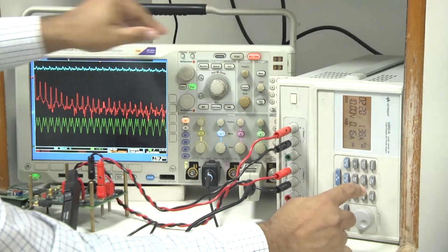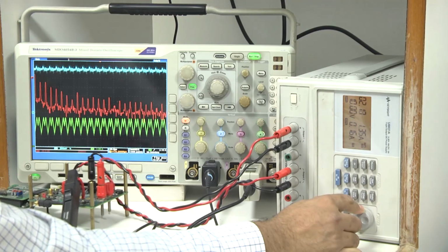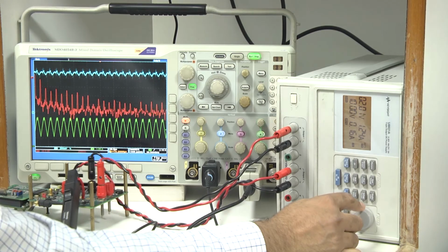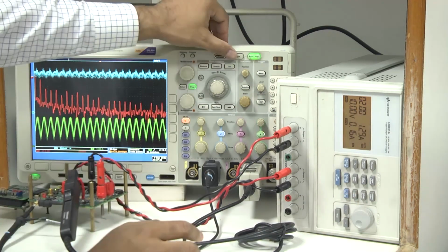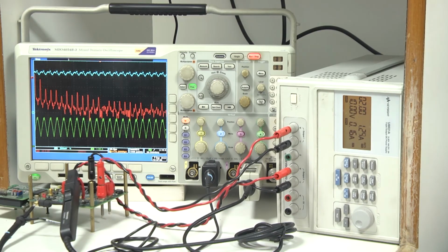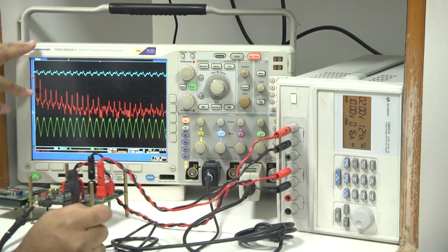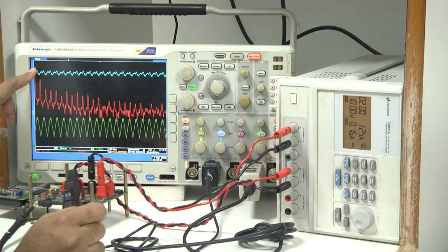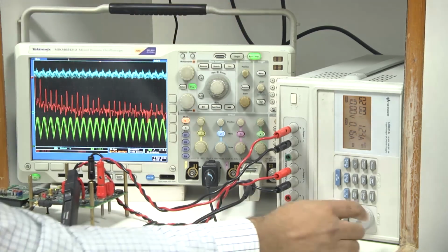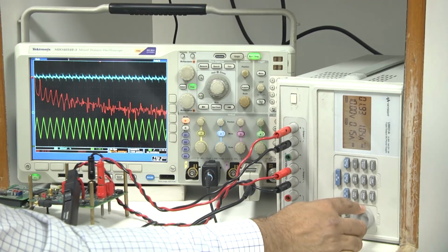Then we are going to reduce this voltage to 2 volt. At 2 volt, you will see that the instability is almost like 100 kilohertz, but there is still some switching on and off, and the spectral peak is now very sharp at 100 kilohertz. The sub-harmonic is very dominant, and you can see that the peak-to-peak ripple has drastically increased, so it will affect the RMS current. Now if we further go to 1.9 volt,